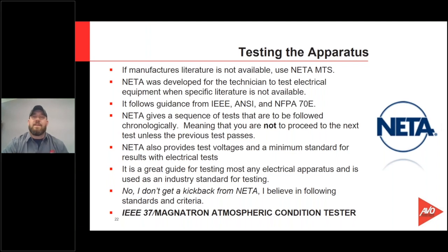But a lot of times what I'll do is preach and teach that, hey, look, I know with an overvoltage withstand test, it's a pass or fail test, but we can also record leakage current as well. We want to trend that leakage current, okay? Because these pieces are man-made and eventually they'll fail. So we want to trend that, watching it and making sure we know when it fails and whatnot.